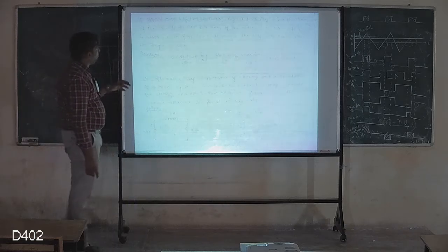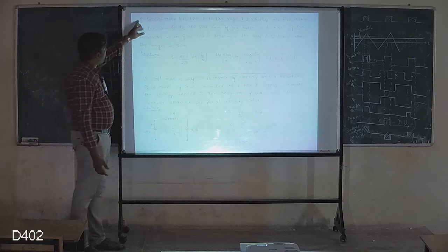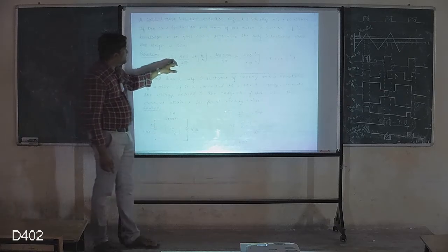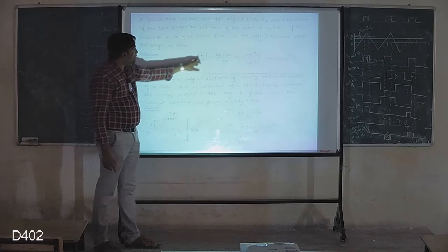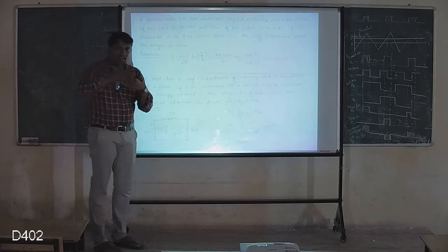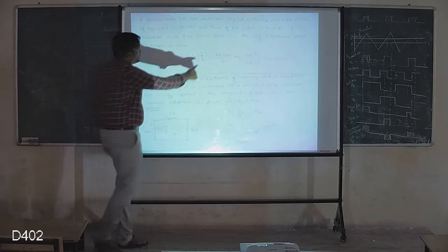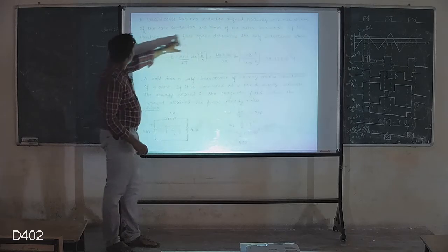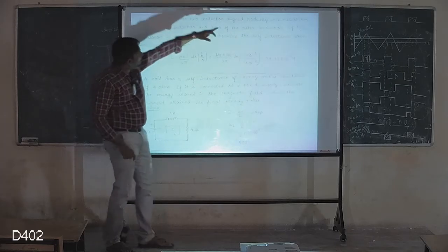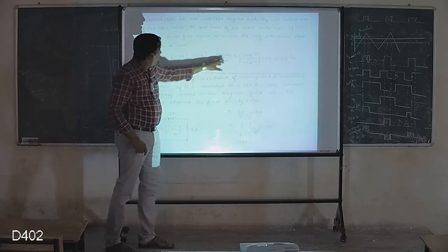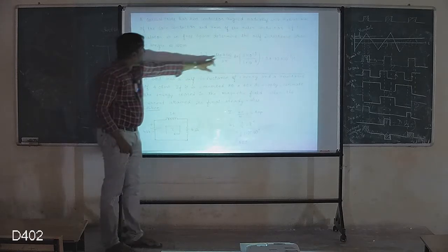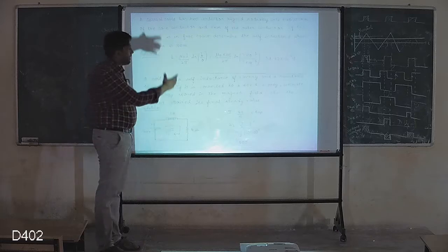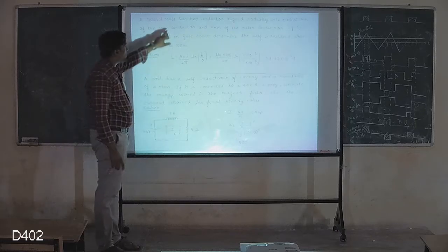Next thing is we are finding the coaxial cable inductance. For that, during the derivation, we understand L is equal to mu naught L by 2 pi ln B by A. So this is between inner and outer conductor. B is given as 7 mm, A is given as about 1 mm, and the length is 100 meter. If I substitute, I will get roughly 39 microhenry. That is the answer for the inductance of the coaxial cable.